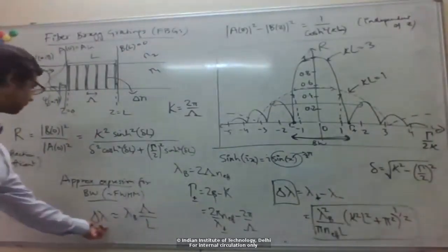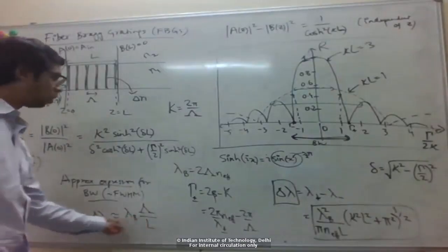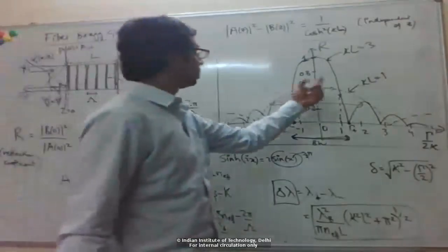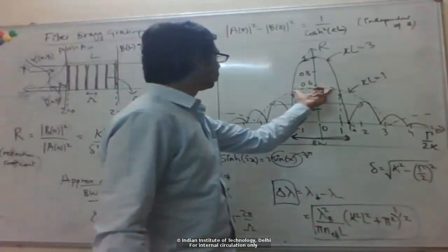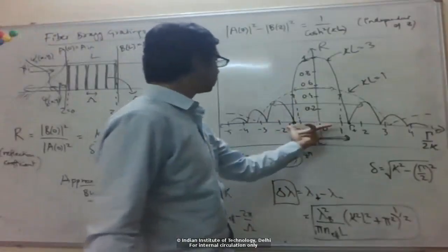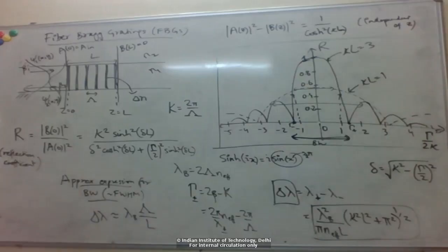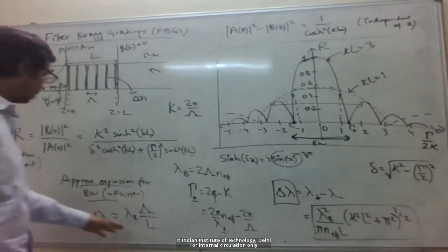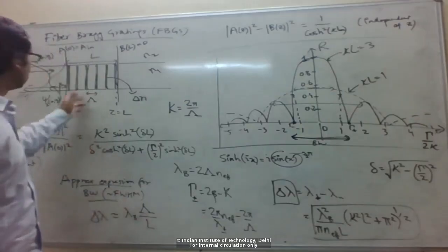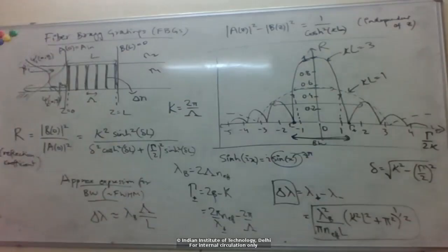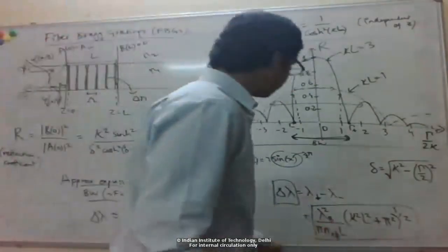Okay. So this expression for the bandwidth typically will give you a lower value than this, right? Because this approximates the full width at half max, whereas this one estimates where it goes down to 0. Okay, from here you can see that if you have a longer grating, then the bandwidth is smaller. Again here, because of the L coming in the denominator.